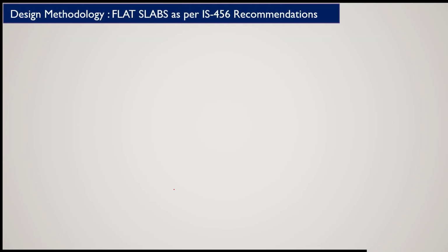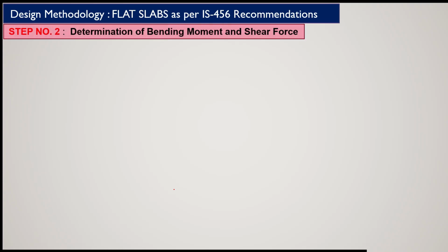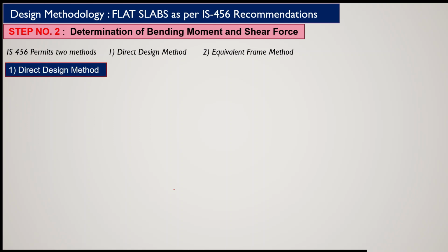Design methodology of flat slab as per IS 456 recommendation, as we have already discussed some part of it. Now step number 2, determination of bending moment and shear force. So here IS 456 permits two methods. Number 1 is direct design method and the second one is the equivalent frame method. So first of all, let us try to understand the first method, direct design method. What are the various guidelines which are given in codal provision,